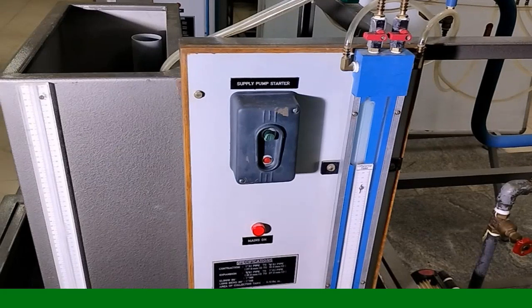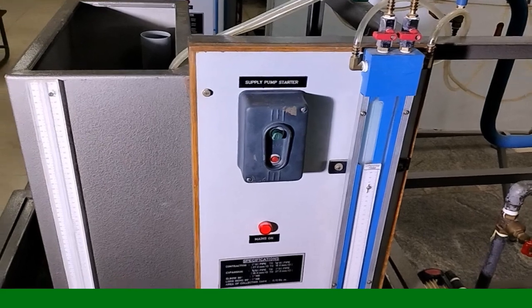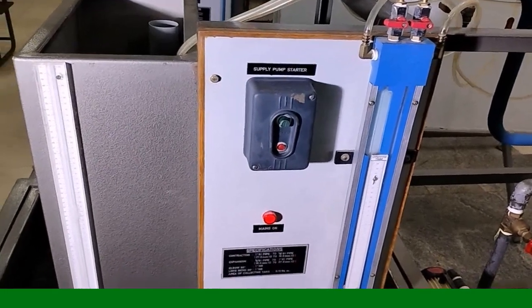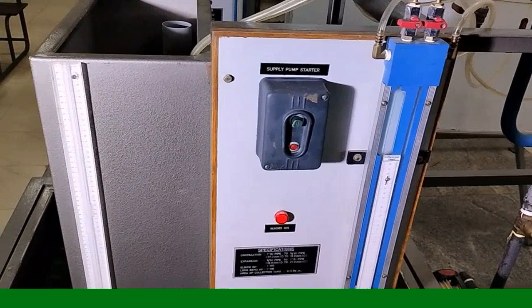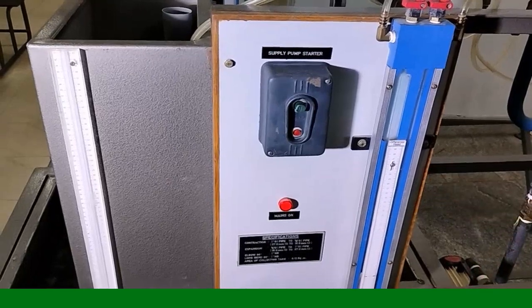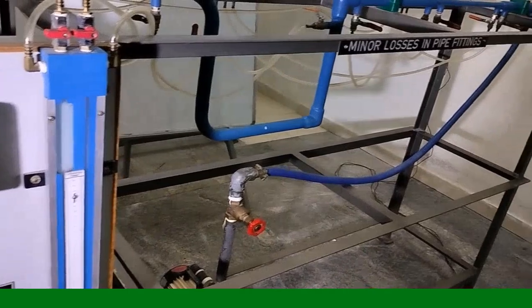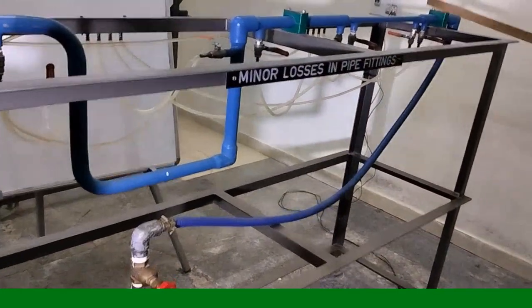Now the experiment we are going to conduct, the mains is on. I am going to switch on the pump. Before running the pump, I am going to once again ensure which experiment I am conducting. Now I am going to conduct the already explained sudden contraction experiment. So I only open this one. The remaining pressure tapping valves are closed.